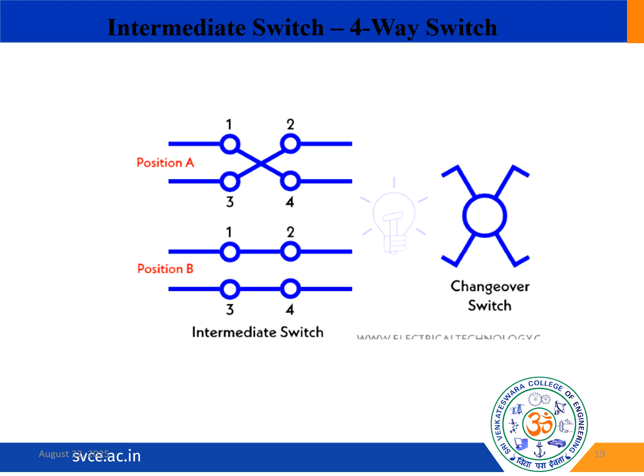When you consider the applications for the intermediate switch, we can have staircase lighting, which controls the light from both the top and bottom of the stairs. And considering large rooms and halls, it also controls a single light from opposite ends, right? So intermediate switches play a key role here. Multi-way switching configurations also enhance convenience and energy efficiency in smart or traditional electrical systems. So we have seen in this diagram what an intermediate switch and a changeover switch are.